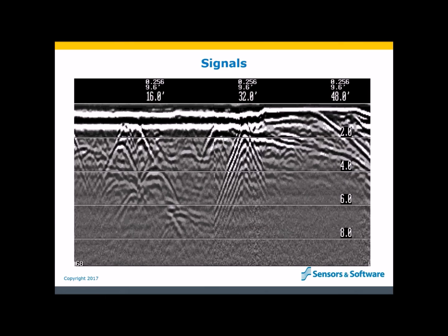Okay, back at the GPR line we're interpreting. Look at the bottom of the line. What is the signal that looks like a snowstorm or an old school TV station not coming in properly? Some of you will know that this is background noise. It's important to remember that a GPR receiver does not only record GPR signals. It records radio signals. So it will also record any radio frequencies in its bandwidth. This is called RF, or radio frequency noise.